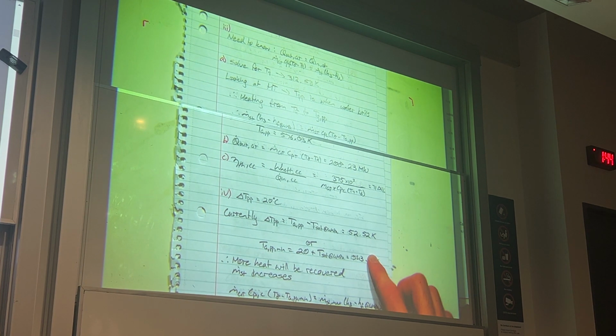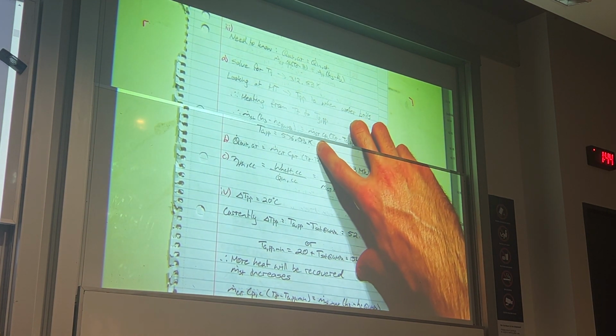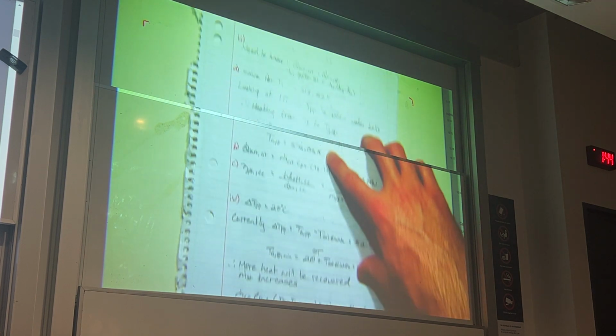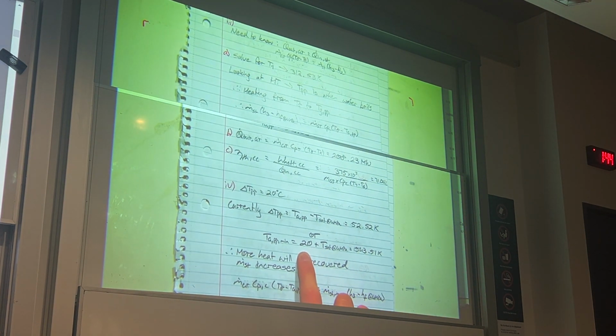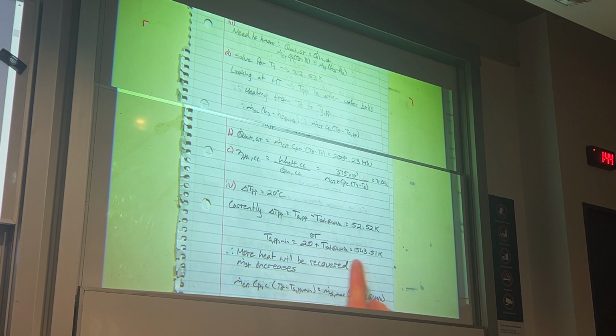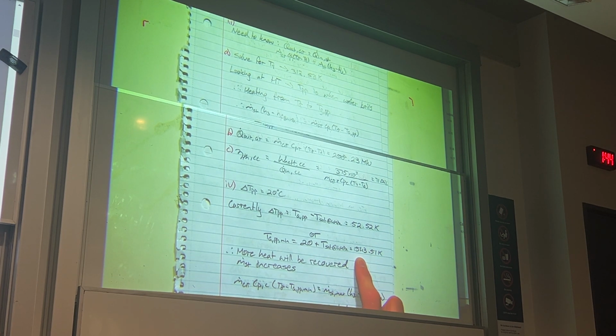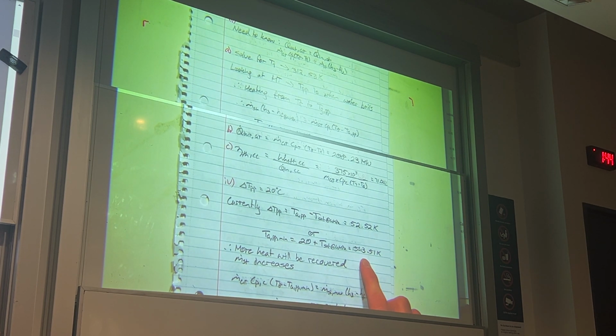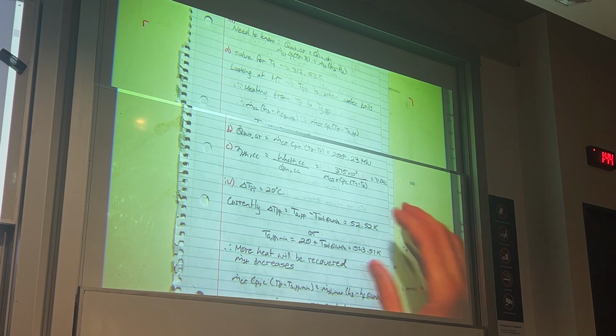So basically we know our pinch point temp is 576.03. So knowing that our delta PP is 20, our minimum pinch point temperature is going to be 543.5 kelvins. So because our pinch point temp's been dropped, we're actually exchanging more heat.